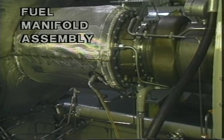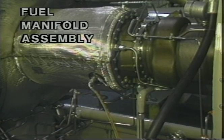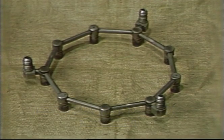The fuel manifold and nozzle assembly is the last component that gas passes through prior to entering the combustor. You may have noticed that this engine is constructed somewhat differently than the one you saw in the first module. Both engines use gas fuel, but this engine has the standard gas fuel manifold, whereas the other engine was equipped with a dual fuel manifold. The assembly consists of a two-piece manifold and 9 fuel nozzles.